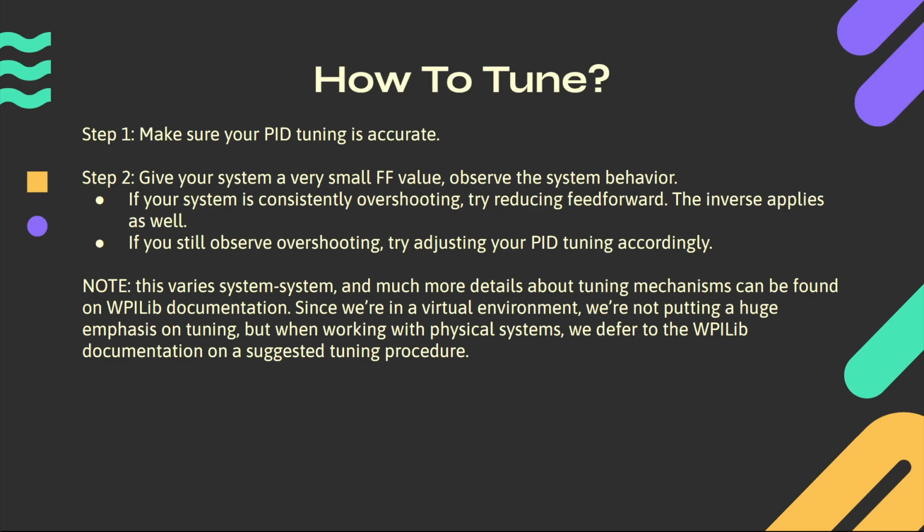And so if you really want to practice the implementation of it, you could just take one motor and apply the feed forward and try to get that motor spinning to like 2000 RPM, right? And then you can see for yourself how changing the feed forward value impacts how the motor spins and behaves, especially looking at those charts, is really what's going to teach you best in terms of how to tune, right? So if you've got access to your shop, head over, grab a motor, and just write code using feed forward control, and just see what changing the PID values and changing the feed forward values does. That's going to be the best way for you to learn, even better than reading other teams' documentation or the WPI Lib documentation, right?